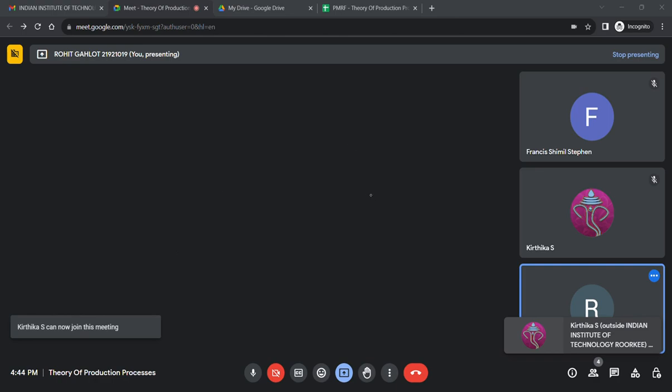So just for the others, I will solve this. The modulus of the riser is 1.2 times the modulus of the casting, as given here. So I will write the modulus of the riser as the volume of the riser divided by the area of the riser.